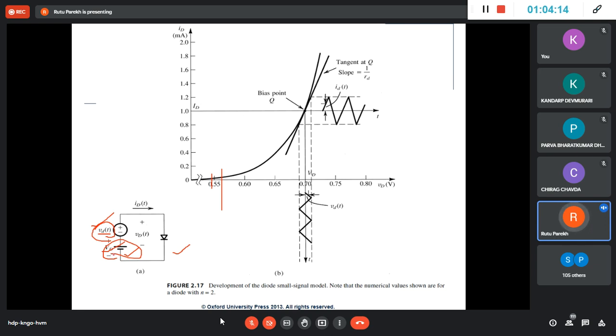But when you are processing a signal, in signal processing, the signals are weak. They are of the order of millivolts. If you give that signal directly to the diode and you think it will rectify, no. So you give enough energy to the diode first if the signal is weak, and that is biasing. Understood?